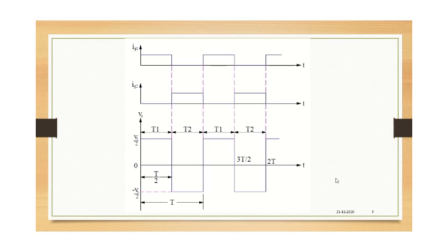If you continue like that, next you trigger T1, T1 will be conducting, so the output across the load will be Vs by 2. Then when T2 is fired, the output will be minus Vs by 2. So what you are getting is a square wave which is oscillating.